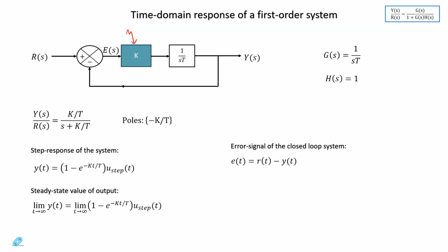If you remember, I had written K(s). Suppose it is not K(s), but just some constant number. What it does is take the error as input, multiply K with it and give that as output to the plant. This K is in your hand, you can change this K, and it has nothing to do with the actual plant because you are creating it.